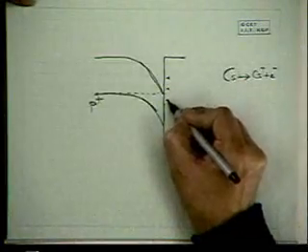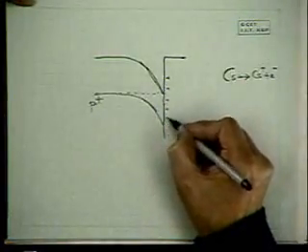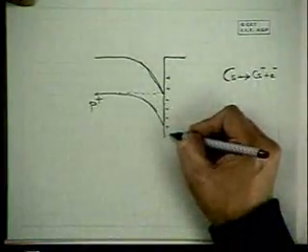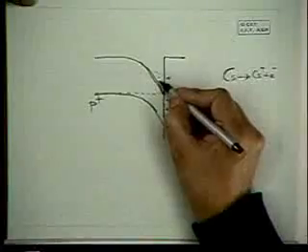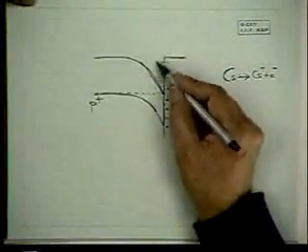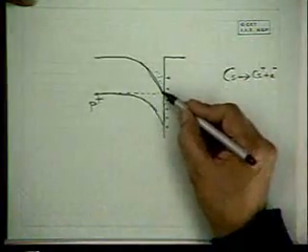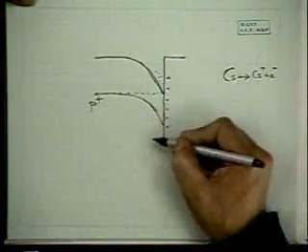So this cesium plus gives rise to a sheath of positive charge here. It is this positive charge which causes the band bending and causes a strong inversion layer formation at the surface. Right?